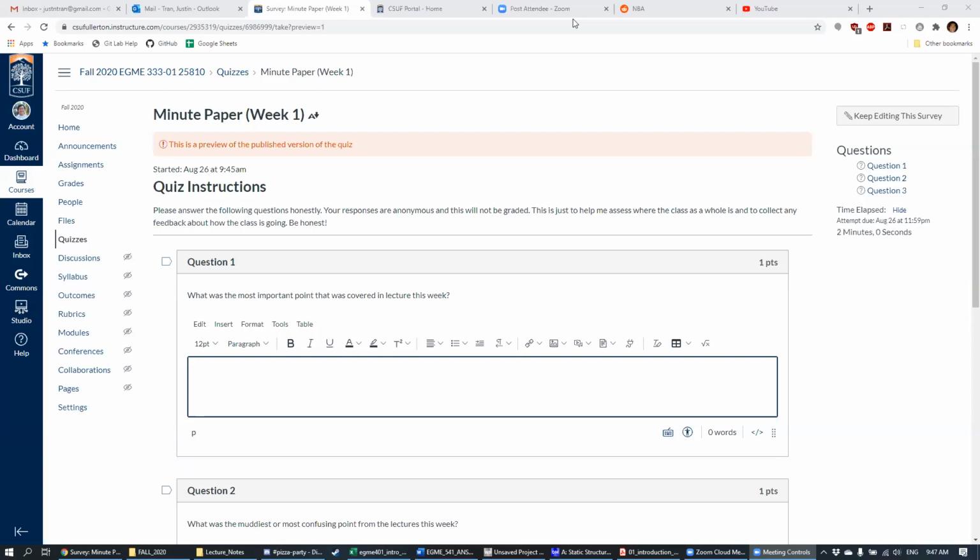All right, so the question is, the book states real fluids always stick to solid boundaries that contain them, so something like sand wouldn't be a real fluid. Sand is a very interesting thing, because it does exhibit a lot of fluid-like properties, but it has a different technical term. Sand does typically stick, but only in a very small layer. And that's true for fluids too.